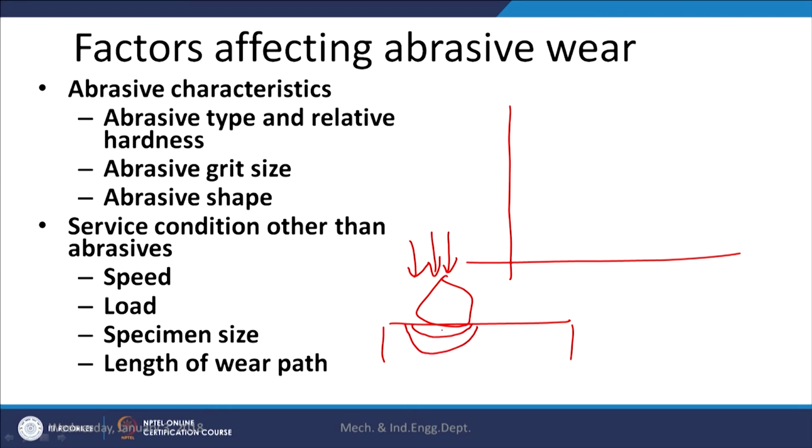Increasing depth of indentation will simply increase the abrasive wear rate. But if with the increase of the load the abrasive starts getting fractured or damaged, then the increase in the abrasive wear rate will be reduced.